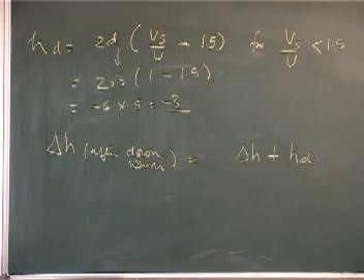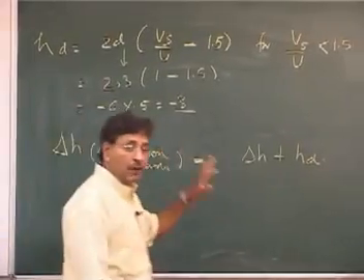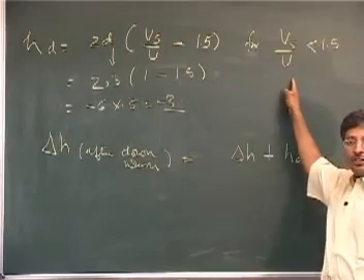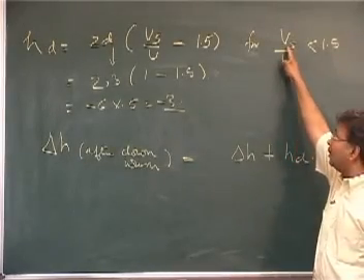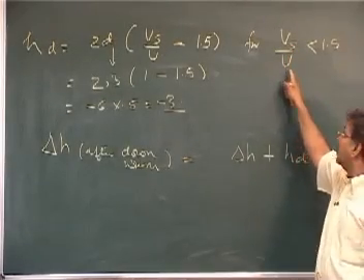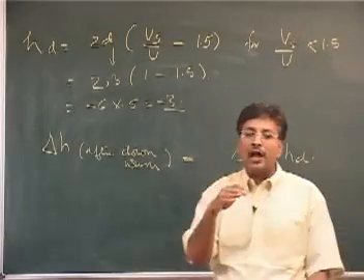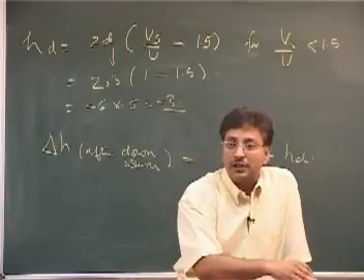Just remember, you do not apply this correction if the ratio of your exit velocity to horizontal wind speed is more than 1.5. It means the horizontal wind will not have the effect of bringing the pollutants down.